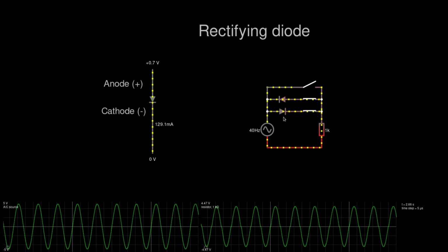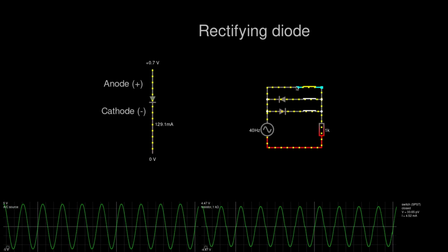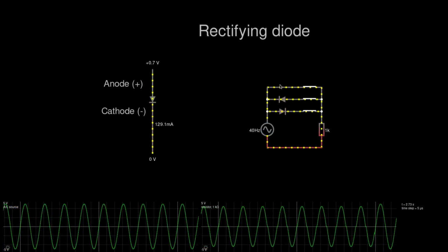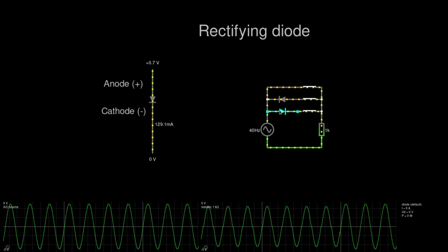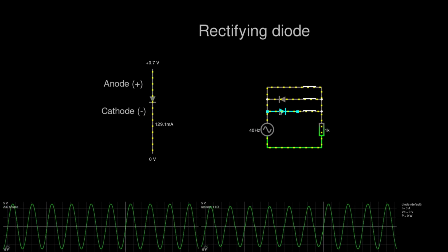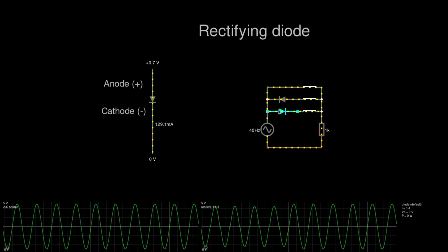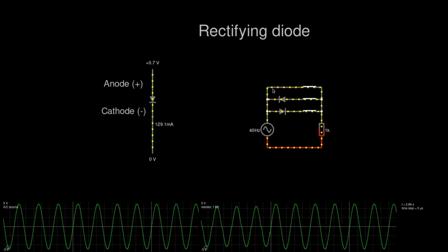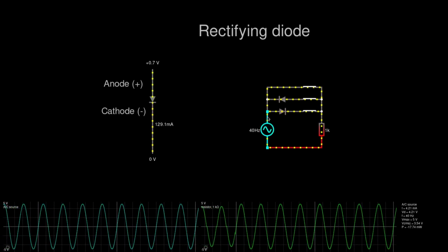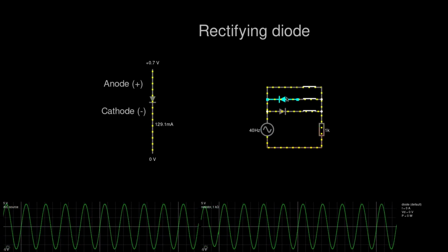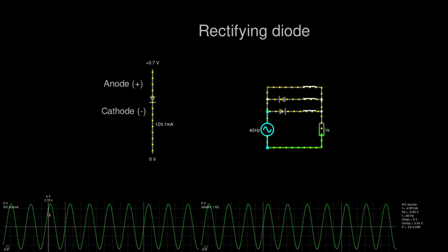And let's say I'll put the upper switch back in action, we can see the current is going through the path of least resistance in this case, because even the diodes that are forward biased still resist the current more than just the wire over here. So if we bypass the diodes, we can see that the signals are equal. Both have plus minus 5 volts over here.